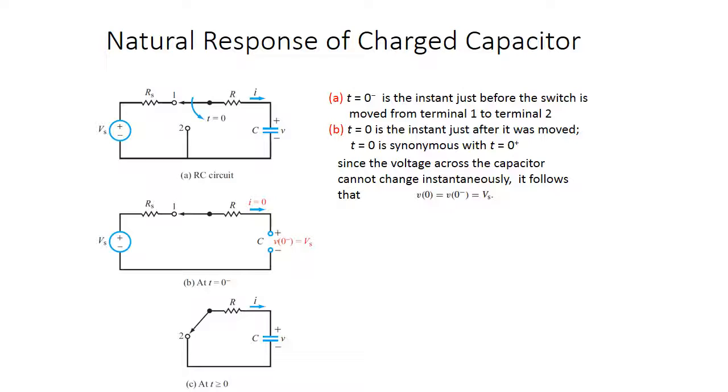So essentially that capacitor is going to be providing voltage because it's not instantaneous. It's a function of the capacitor and the resistor. And so this is going to slowly empty the capacitor out, depending on the resistor's value. So different resistor values will allow you to change this differently. In general, the smaller the resistor value, the faster this will happen. Because if there's just a wire there and there's no resistor, that charge is going to immediately flow from the positive to the negative through those wires. You're going to get a spark and it's going to be discharged.